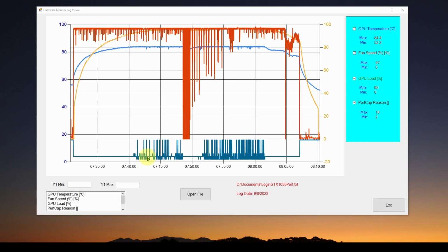So it might be easiest if we first look at the thermal performance, where it happens quite a bit here. You can see it's going down to 2 and up to 6, which means there's a lot of thermal limitations going on. And especially here in the last 2/3 of the render, a lot of this is thermal and thermal plus the voltage versus frequency. So it might be easiest to just say, hey, maybe we can fix the thermal problems, and instead of having a 36-minute render, maybe we can get it down to 2 minutes. Wouldn't that be cool? So let's see if we can figure out some way to improve the thermal performance and maybe help the performance of our render.